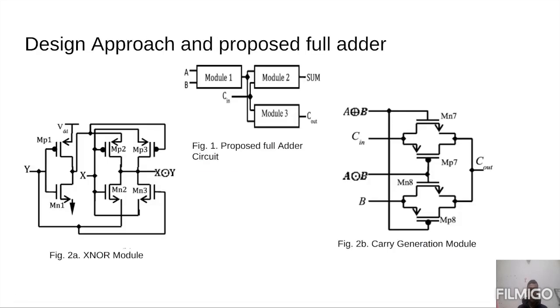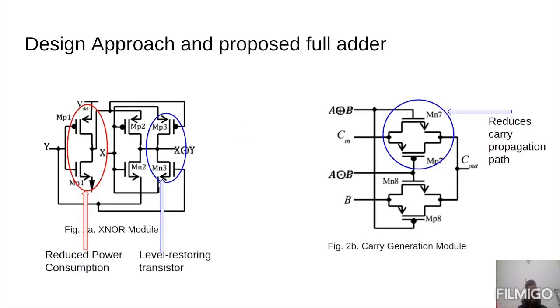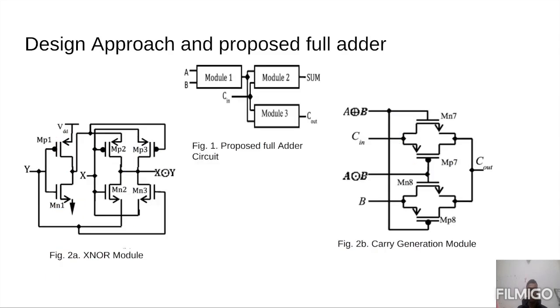The design approach of the proposed full adder is classified into three modules: module 1, module 2, and module 3, and they have different outcomes. We're using the XNOR module, that is module 1 and module 2. Combining both of these XNOR modules, we get the sum function, and then we get the C out function.